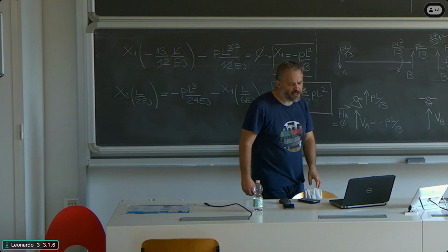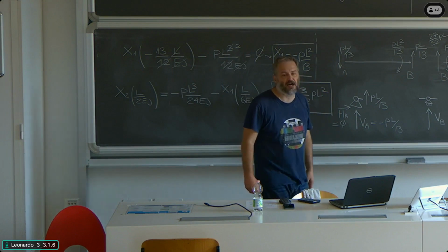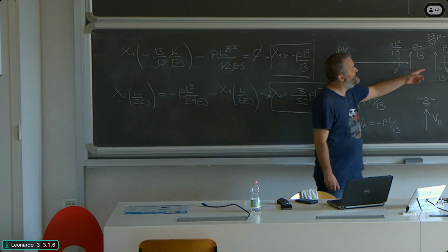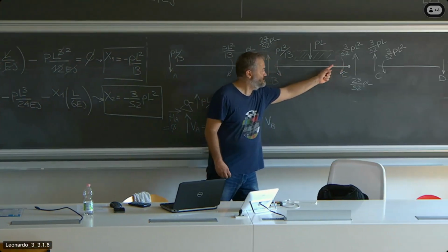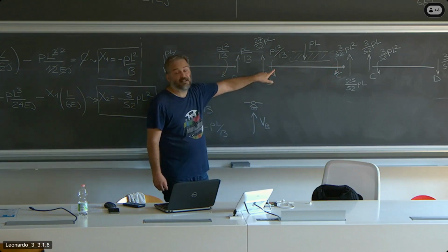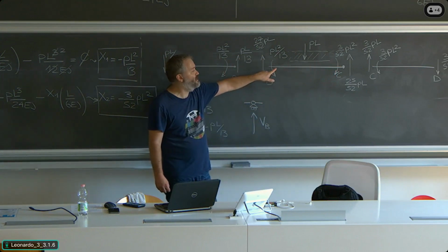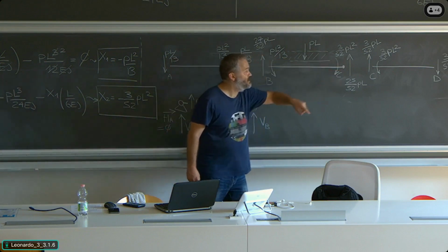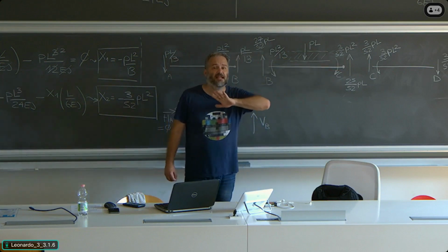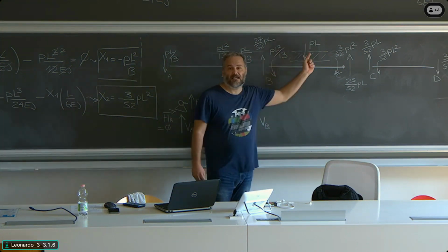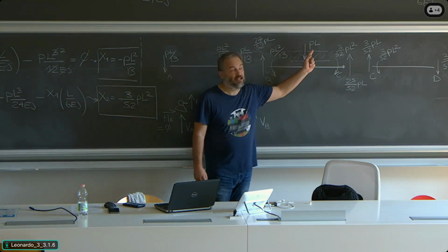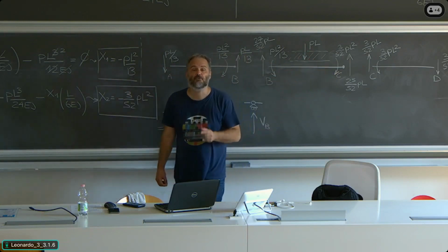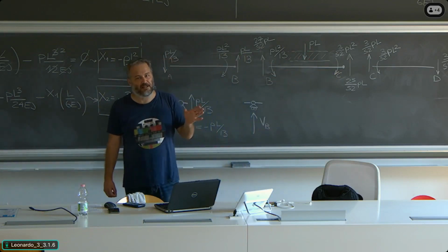Can you please re-explain how to see if the values are right? Is a question from the audience. Yeah, I just mentioned that whatever the bending moments you obtain are, so in this case I got this and this value, one basic requirement is that if you have a load applied like this, whose value is PL, the two forces at the end should have a sum which is equal to PL.